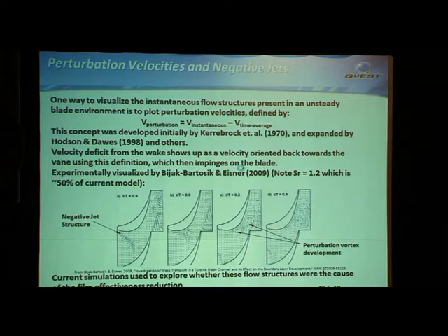These are actually experimental pictures shown down here, where if you post-process your results to look at what they call a perturbation velocity, where you subtract off the mean velocity field, you can get these things called negative jets. This is actually the wake coming off of the upstream airfoil, and you can see that negative jet impinges on the suction surface of the airfoil. When we saw this, we thought, I wonder if that's what's happening on our blade, on the pressure side.